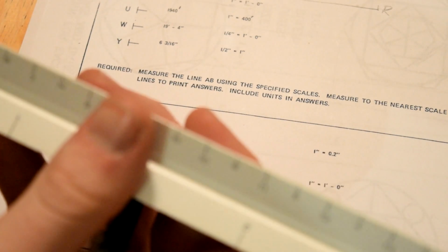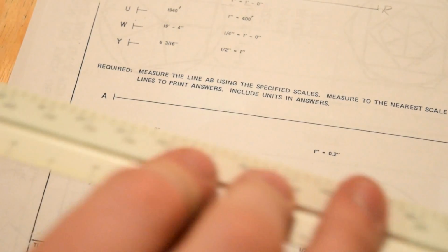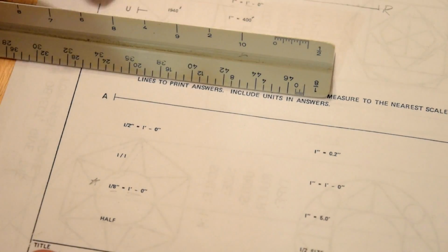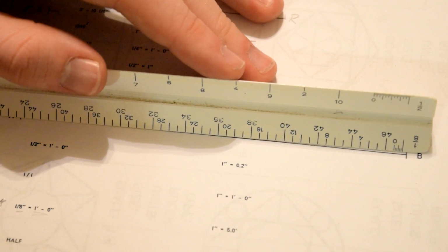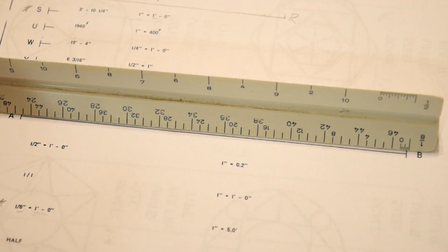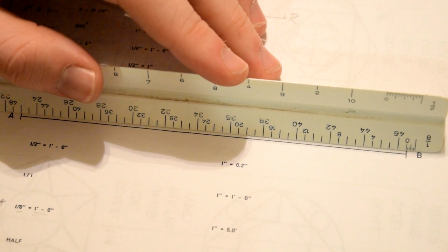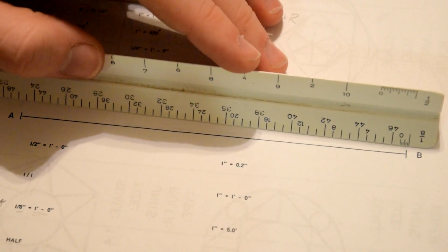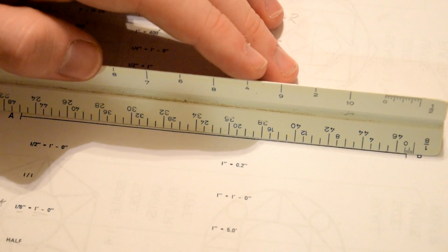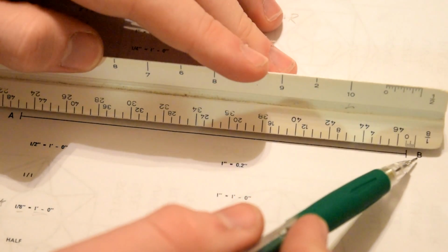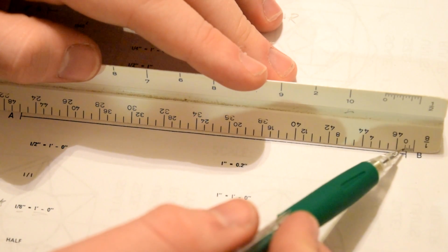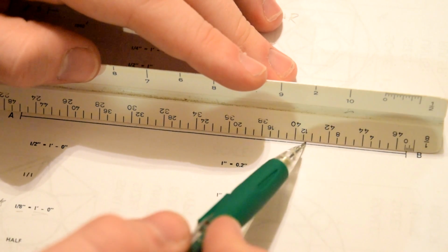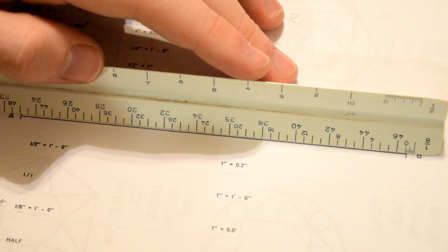So I'm going to use my architect scale and find the 1/8. There it is. I'm going to have to do it upside down again, so it will show up on the paper. Okay, so I'm going to measure this line. 1/8 of an inch equals a foot. So I'll start with 0, and we know that since 1/8 of an inch is on this side, the 0 mark is a little shorter. So I'm working with these shorter lines. So there's 4/8, and since 1/8 of an inch equals a foot, that would be 4 feet, 8 feet, 12 feet. Okay, so we come out to the end.